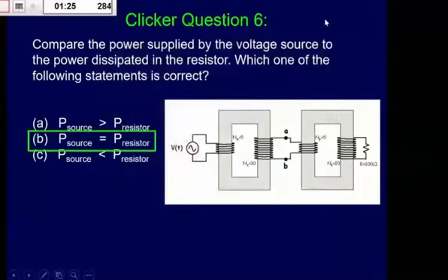The other idea with these things, again assuming an ideal transformer, is that the power delivered is I times V, and that's going to be the same on both sides of this transformer. It's one of the positive aspects of the transformer that it's super efficient, as close to 100% as you can get. So you don't lose energy in this process.